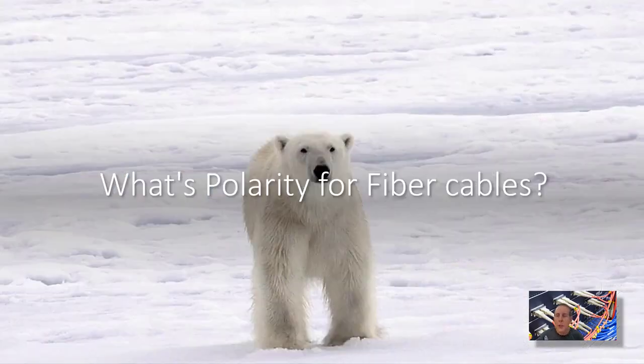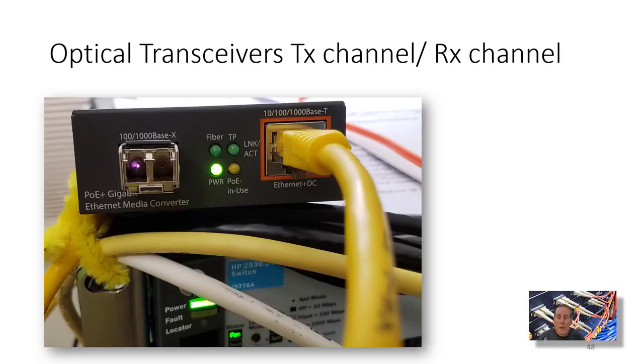So what is polarity in regard to fiber optic cables? Well, it isn't about polar bears, and it's not about the North Pole. Optical transceivers have a transmit side and a receive side. If you look at the optical transceiver inside my media converter, you see that one side is totally dark. That's the sensor side of the optical transceiver. On the other side, you see a little purple light shining out. That's the transmit channel of the optical transceiver.